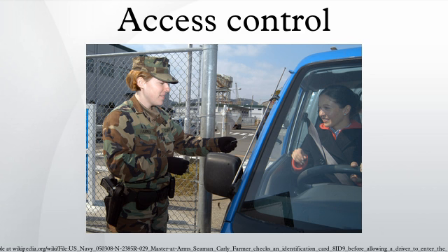Spoofing locking hardware is fairly simple and more elegant than levering. A strong magnet can operate the solenoid controlling bolts in electric locking hardware. Motor locks, more prevalent in Europe than in the US, are also susceptible to this attack using a donut-shaped magnet. It is also possible to manipulate the power to the lock either by removing or adding current.